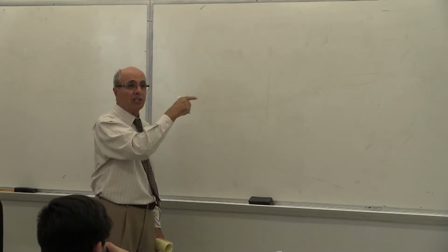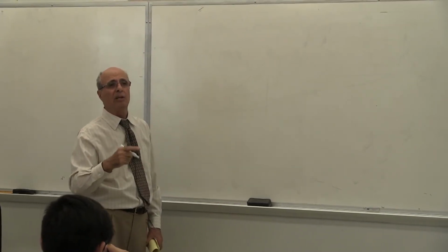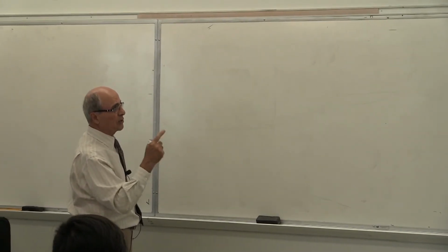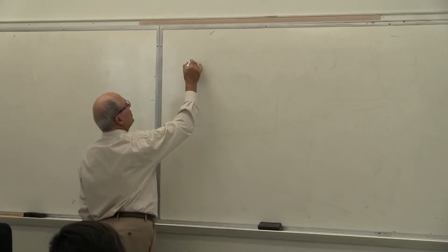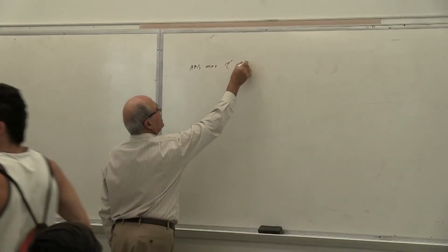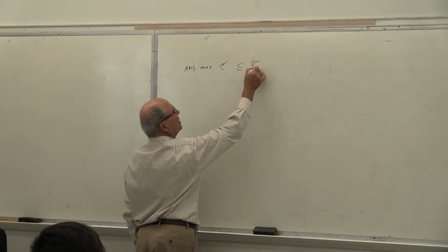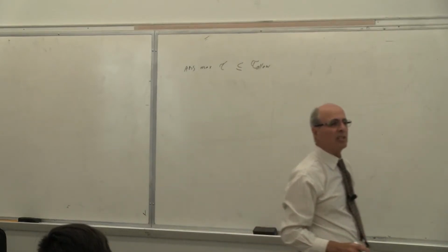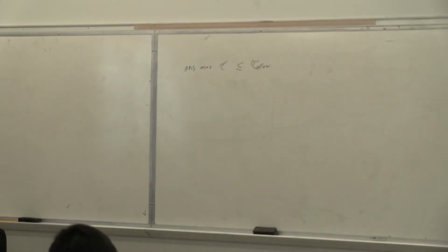Notice we use that idea in the beam design. We should use that idea in the shaft design. However, you will see what happened through that system. But at the end, we calculate absolute maximum tau, and if that is less than tau allowable, this is what I said at the end of class, we call that shear stress criteria, yes or no? If you look at all the homework that I selected for you, it says use the shear stress criteria. Have you seen that sentence there? No, not yet, because you haven't looked at it.